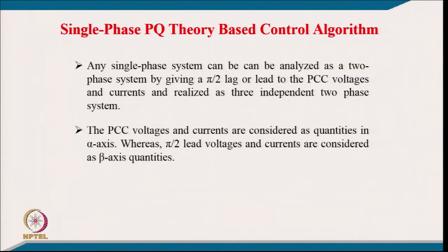Well, another control is based on the single phase PQ theory based control algorithm. It is interesting, it is a modification of the instantaneous reactive power theory, normally used for single phase, and we see how we can extend it to three phase. For single phase you can use it directly, but for three phase we have to modify it for every phase.